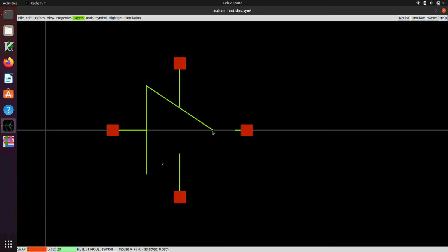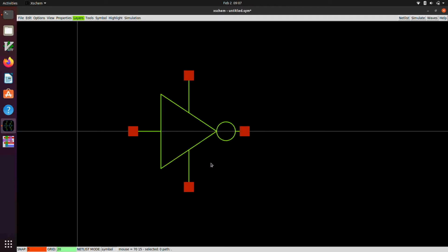So I'm going to hit Control-Shift-C, and you can see now I have a little rubber banding line here, and that lets you put a second point on the circle, which I'm going to put over here at the opposite of the diameter. And then the third point is a point that's going to be on the circle. It takes a little bit of while to get used to how to draw a circle with this thing. But there's my circle.